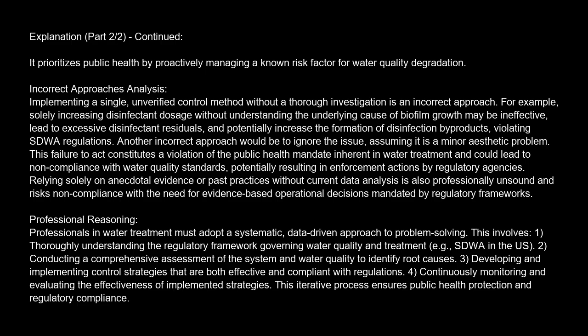Incorrect approach analysis. Implementing a single, unverified control method without a thorough investigation is an incorrect approach. For example, solely increasing disinfectant dosage without understanding the underlying cause of biofilm growth may be ineffective, lead to excessive disinfectant residuals, and potentially increase the formation of disinfection byproducts, violating SDWA regulations.